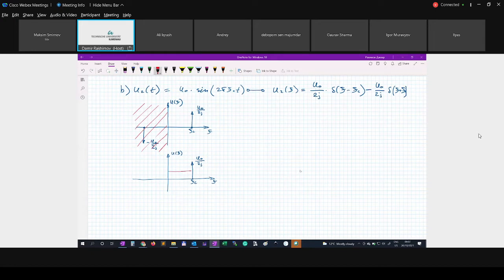with respect to which we perform the bandpass to low pass transformation to 0. And here is important, I should point your attention that depending on the frequency with respect to which we perform the transformation, you may have different results. And here we perform the transformation with respect to frequency Fc. As a result, we move this delta pulse from carrier frequency Fc to 0.